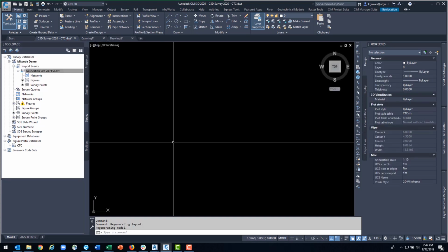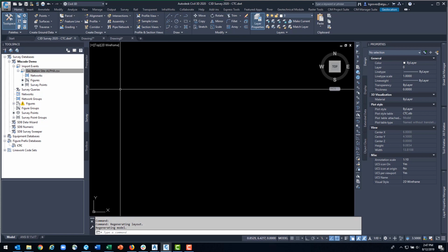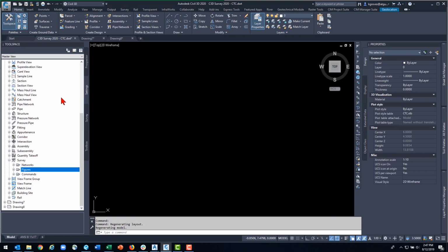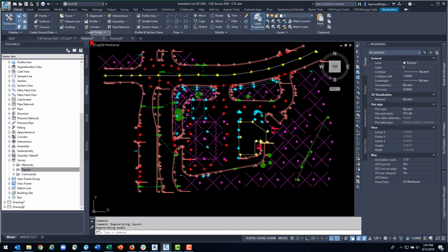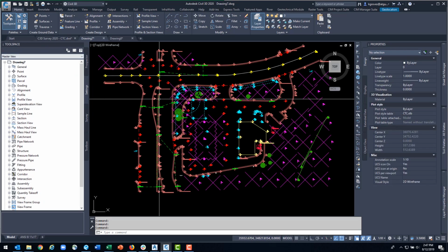As always, the best practice for making template improvements is to create your styles, or what you think those styles need to be, inside your template. Save it, and then create a new drawing based off of that template in order to test.